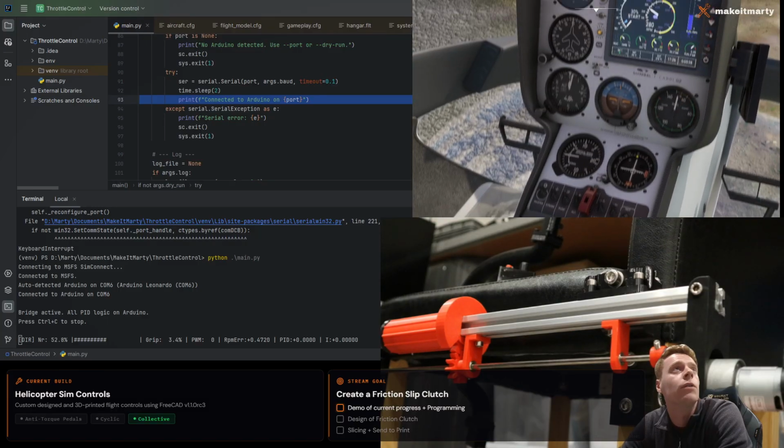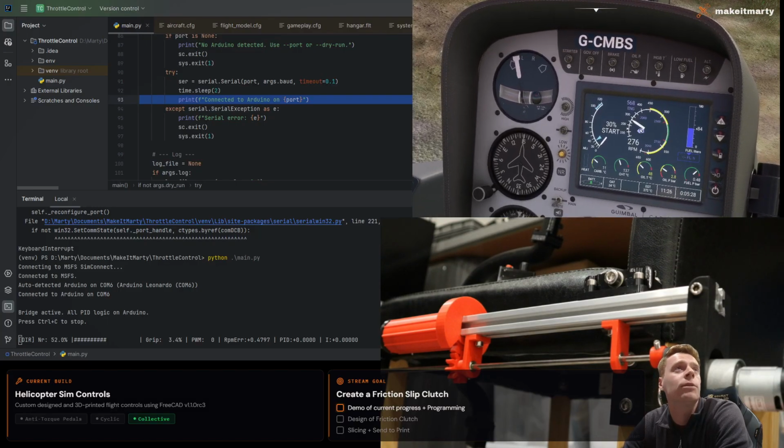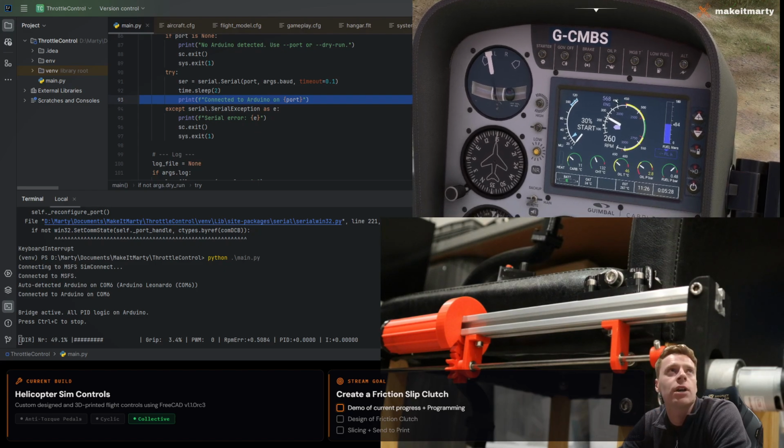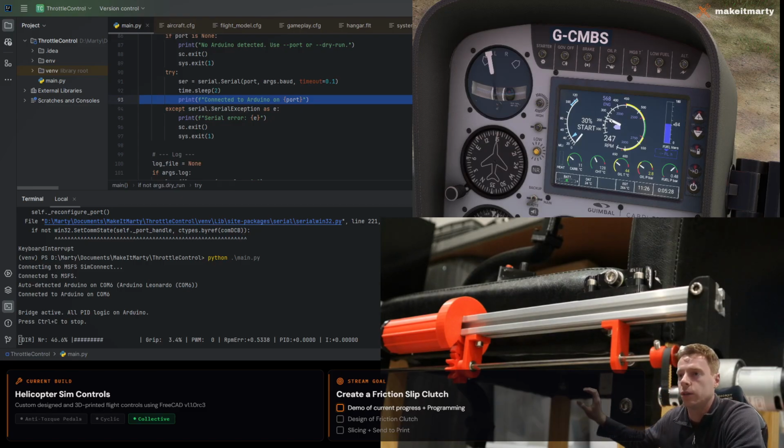There you go, hopefully. Right, so the governor's enabled. And with this type of helicopter again, it engages around 400 RPM or 2000 engine RPM. So what we can do physically is we'll ride the throttle up, and then what we expect to happen is at around 400 RPM, it should then take over and then settle at 530.